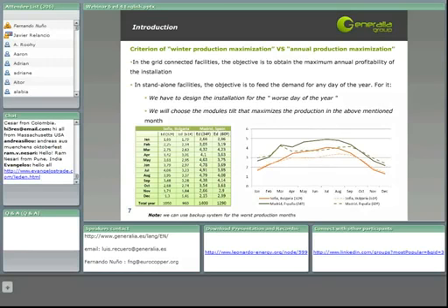But if we choose a different tilt, we can optimize the production during this month and get it to 2.4 kilowatt hours per day. Even if we are losing production during the total year, we have to consider that this might be interesting for us, because maybe we don't need so much production during the summer days.